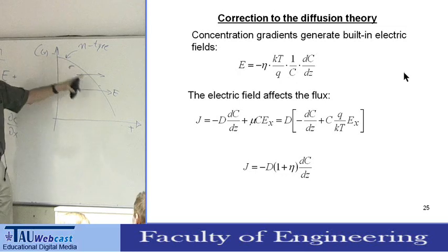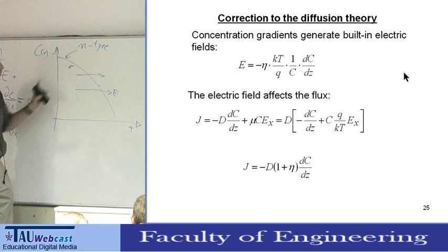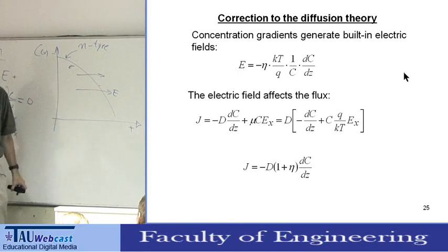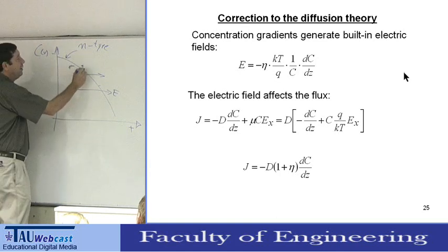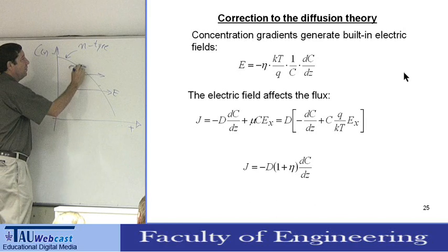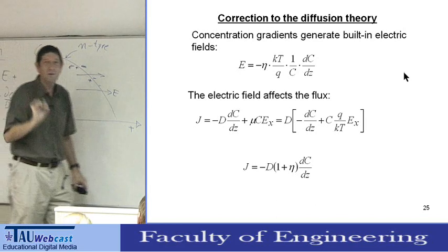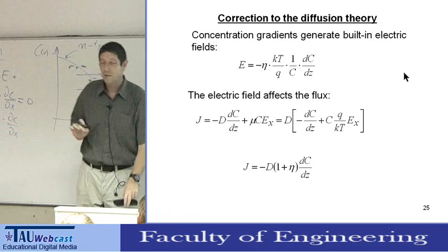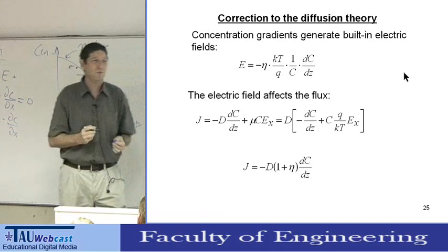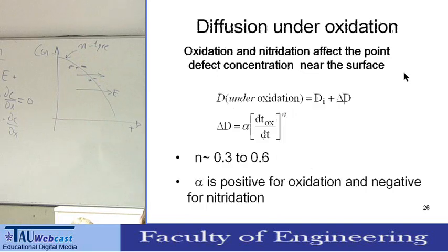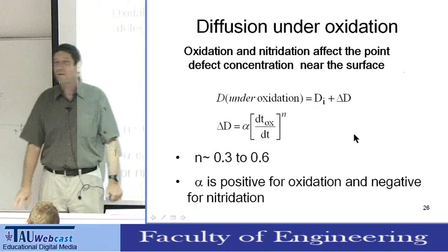And because the n-type dopant are positive, they will go into, and their diffusivity will be enhanced. And the reason it will be enhanced because we're actually generating a dipole here. Minus, plus, minus, plus. You can think about it as there's a very small dipole which actually is pulling the atoms. This is called field-enhanced diffusion. But there are other effects that people discover.